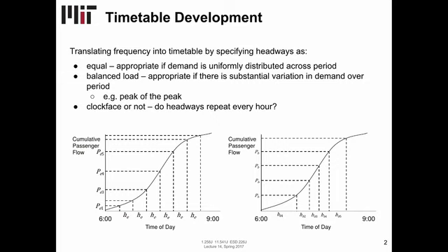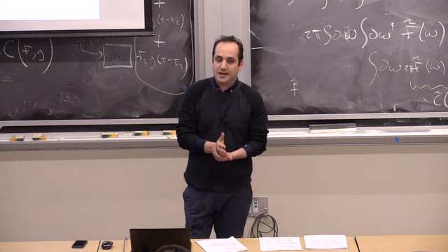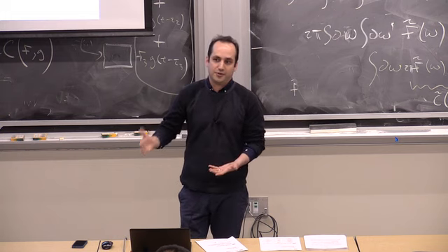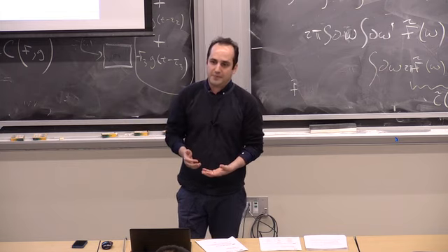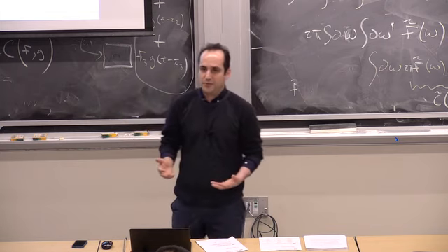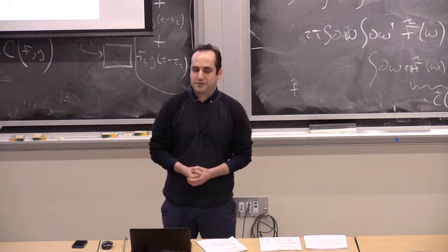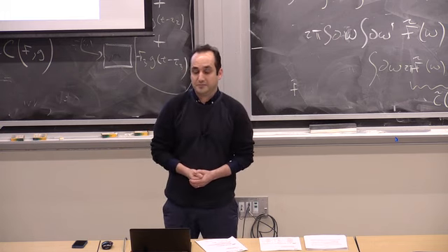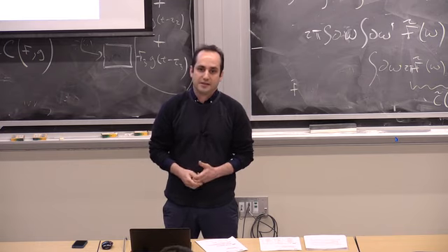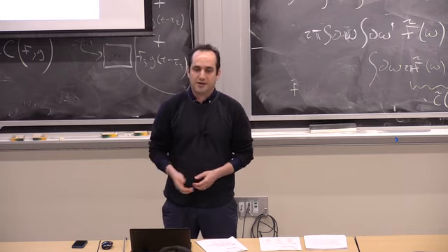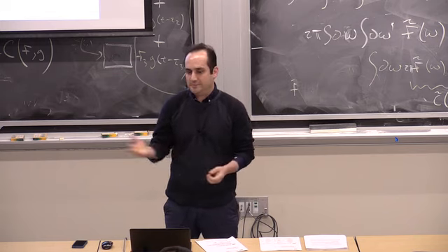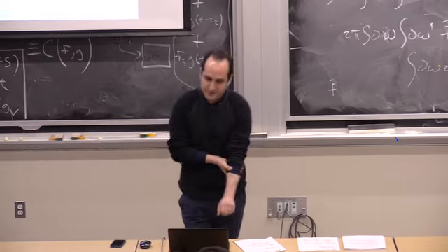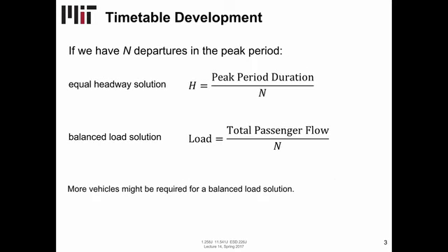That's only the case when the headway is 10, 15, 20, 30 or 60 minutes. And then we would have service every, on minute 1, for example, that would be 7:01, 7:11, 7:21, and so on and so forth. So it's easier for passengers to remember the service that is designed clock face.